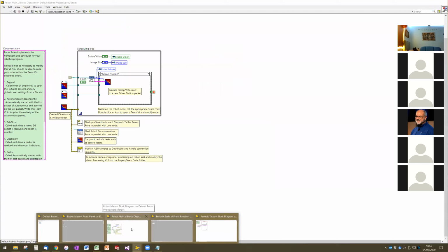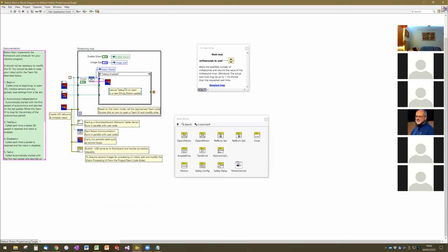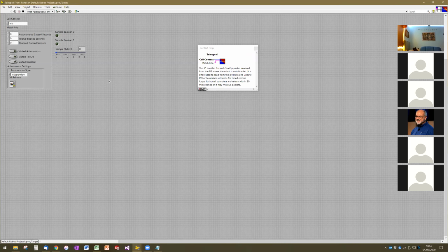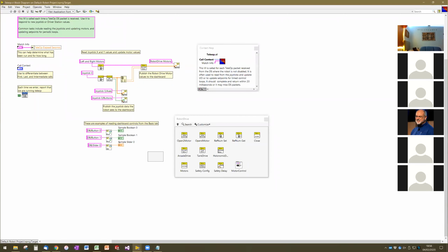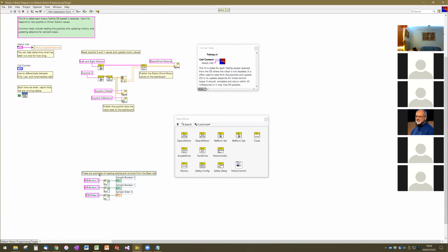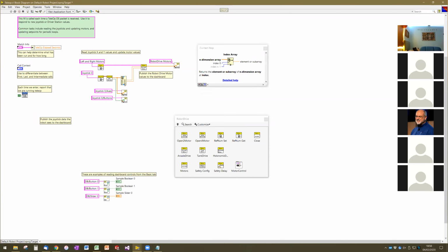Before we send the commands, let's go back and make a decision about how we actually want to command the Talon motor. An option that we have is I'm just going to take the next joystick axis. So this is axis 0 and 1. I'm going to go ahead and grab axis 2. And I'm going to say that we're just going to directly map that joystick axis to the power that we want to send to the motor.